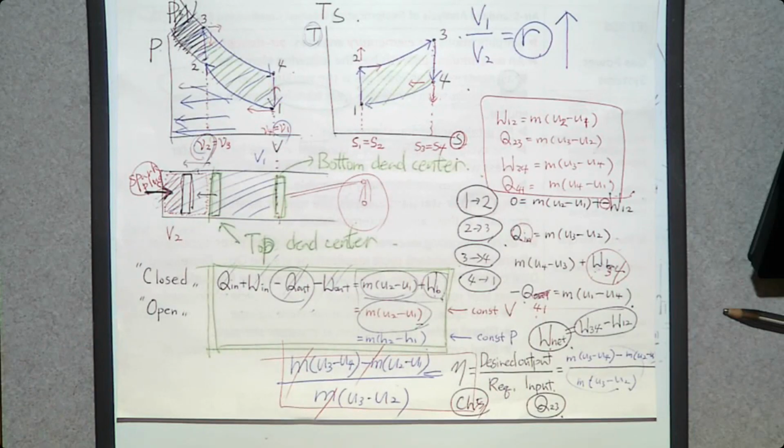So is that good? No, it isn't. That's called knocking in the engine. We are going to discuss it later. Because of that, we cannot just indefinitely increase the compression ratio. There's a limit for this type of engine. Then, is there any way we can improve this compression ratio further without causing that problem?